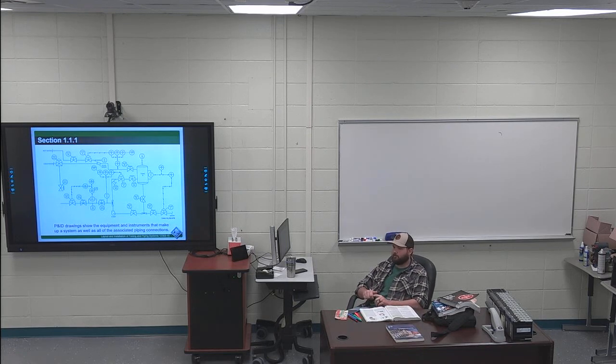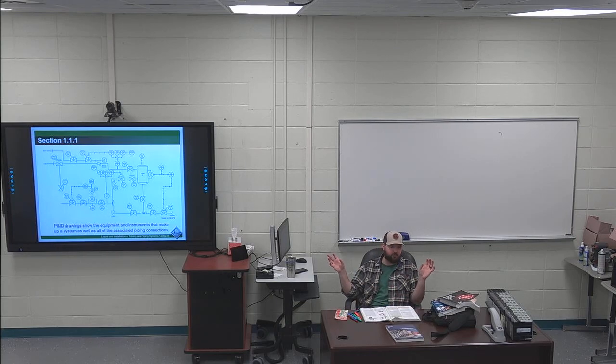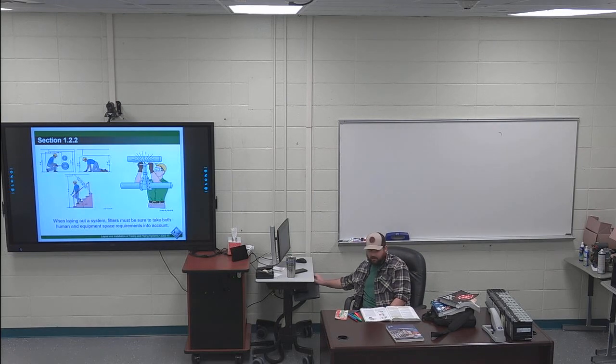It's happening over and over again. I know people that have put in instrumentation, refrigerant lines, or something like that. Next part of construction, somebody comes in and has to do something to the roof, and those instrument lines have to be moved. So that's poor planning. You have to have a plan, like, this is going here, so my instrument lines can't run here. It almost looks like you're going around something invisible, but that's so that another piece of equipment can be installed. So you always want to make sure you have all the information when installing different lines and stuff like that.